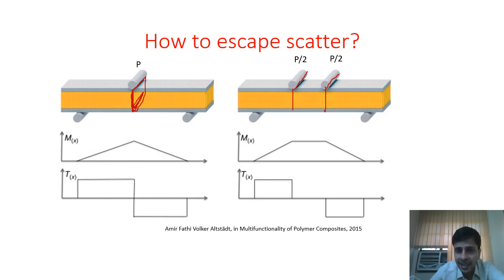Now in this case, I can have fiber and matrix, but since I am applying uniform load over a large amount of area, there is some sort of averaging. So the stress concentration is not at an unknown point where I don't know there is fiber or matrix, but stress is now at a well-defined region where I have both fiber and matrix. So the scatter is much lower.